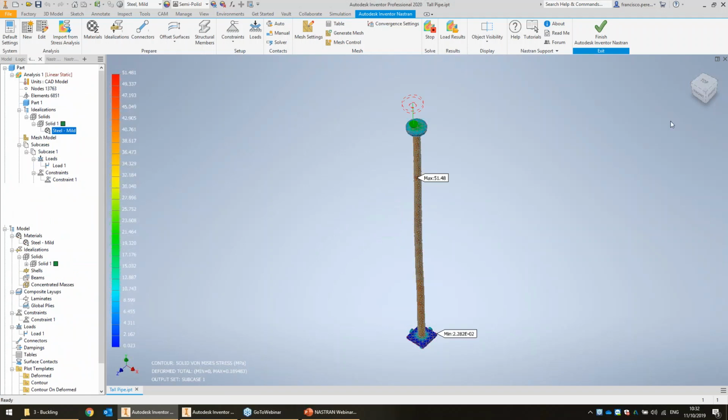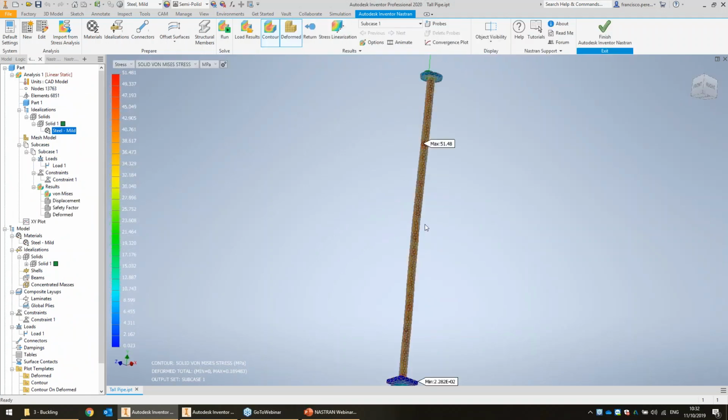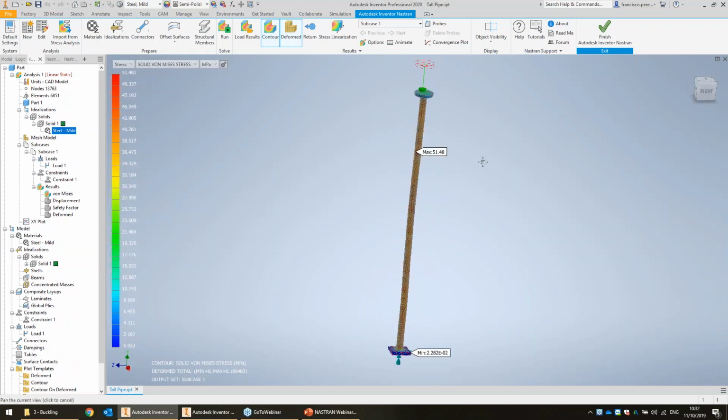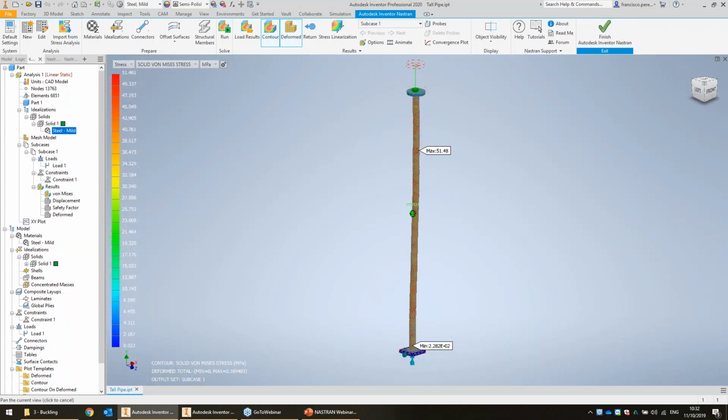And the linear static study is going to lie to us dreadfully. If we trusted this study, we'd say, oh wow, this pole is amazing. What a pole. It can handle the stress very well. We're seeing only 51 megapascals von Mises stress, well below the 200 needed for yield. But reality gets in the way of this nice model, which means it will kink to one side. So how do we calculate that?